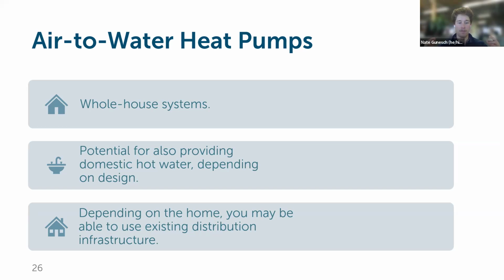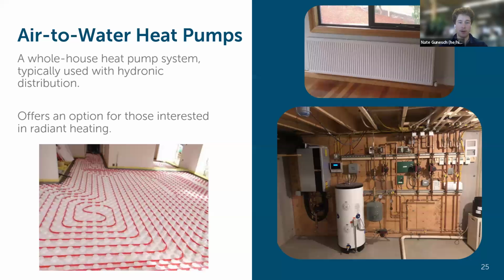Those are designed for boiler temperatures, right? 180 degree water. If you have panel radiators, some people call them European radiators, I'm going to jump back and show you. That's the one on the top right here. These are sized for lower temperature distribution. They have more surface area. They're just more efficient as temperature distributors.